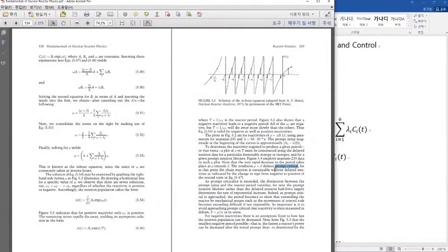So it is very important that the reactivity of a nuclear reactor should be maintained far less than this prompt critical state. When we insert or withdraw reactivity, its magnitude is usually described by how close the inserted reactivity is to the beta value.